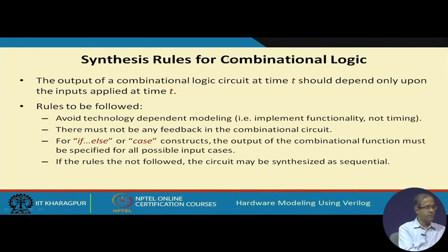So, when you are trying to model combinational logic, there are some rules that need to be followed. First, since you are talking about combinational logic, do not use any kind of technology dependent modeling, specifically details about timing, such as the timing detail using the hash command. Whatever you give during simulation is just meant for carrying out the simulation and interpreting the waveforms that you view after simulation is over.